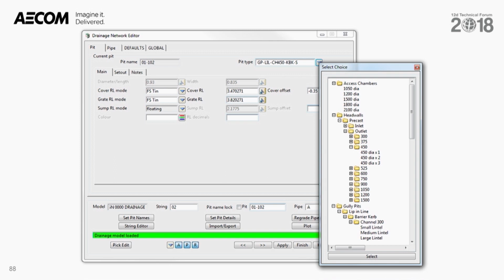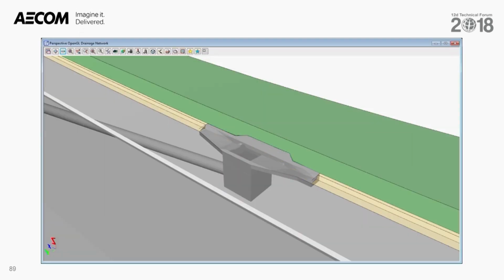Now, the final plan integration of these model drainage structures into our models is adapting the road designs to leave gully pit-shaped holes in our design surfaces and other trimeshes. I tried to be sneaky by including a boundary string in the drainage pit trimesh definition that could then potentially be used with the V14 trimesh cookie cutter, but unfortunately 12D is too smart for that and ignored that when reading it into the drainage trimeshes.